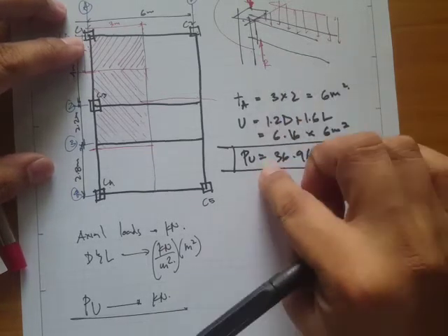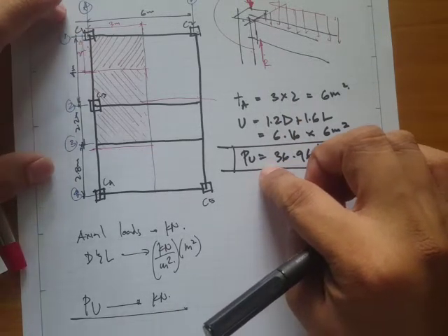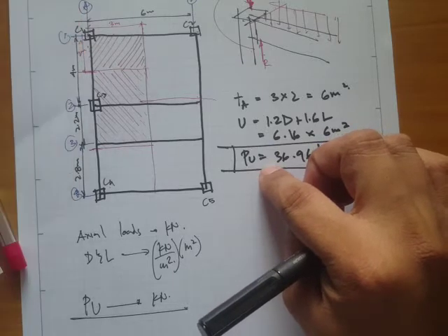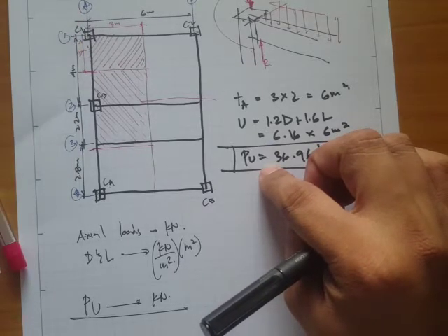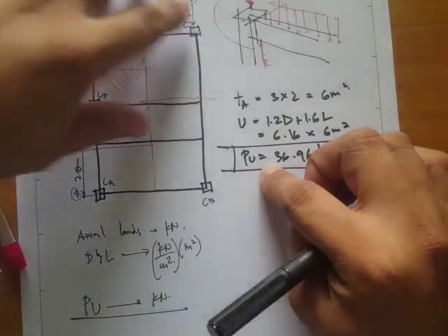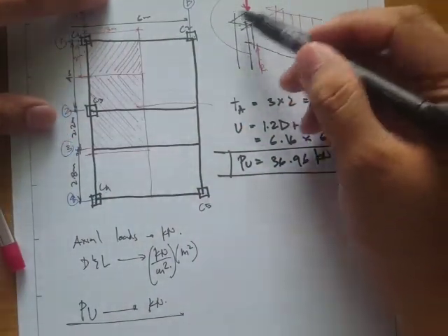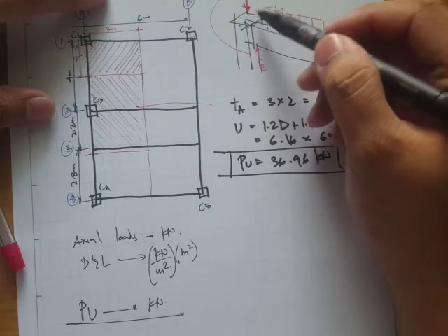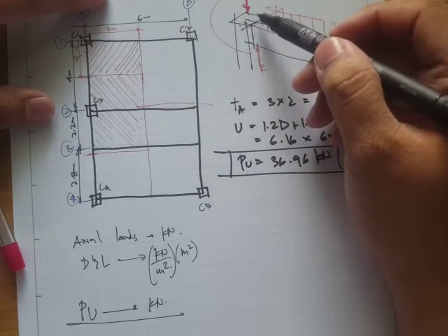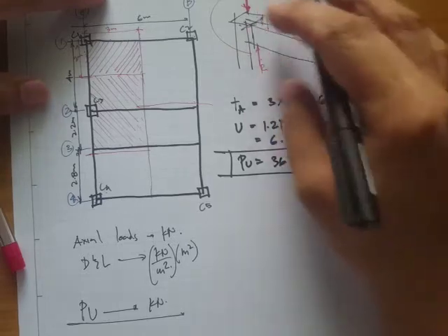Of course, this doesn't include the column weight. That's another computation. You have to include it if it's given; since you have the volume, you can compute the dead load from the weight of this column.